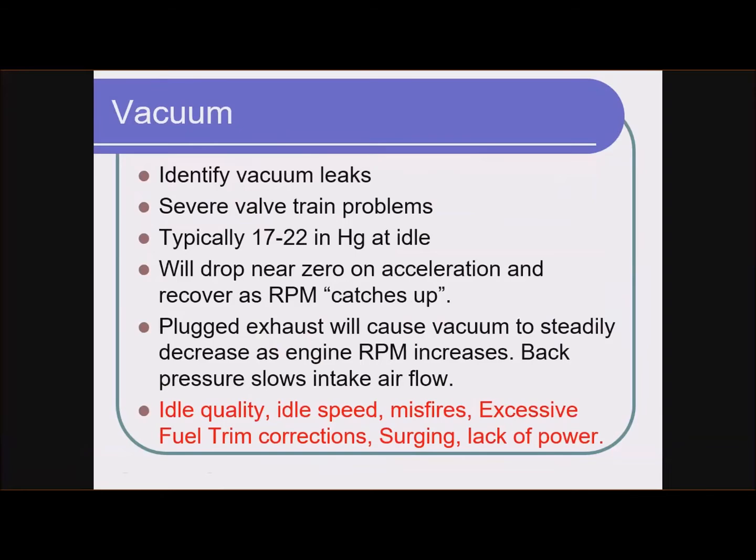And as that pressure backs up, a couple things will happen. One, the needle's moving closer to zero. And then secondly, the engine just won't accelerate, right? This is not the same kind of thing you get when you have a rev limiter on some cars. It's killing fuel injectors to keep the RPM down, and so that's very rough. It's the rev limiter. Other vehicles with an electronic throttle control just refuse to open the throttle plate in order to get the engine speed too high in park. They just won't do it. The computer's limiting the engine RPM because it's in control of the throttle plate.